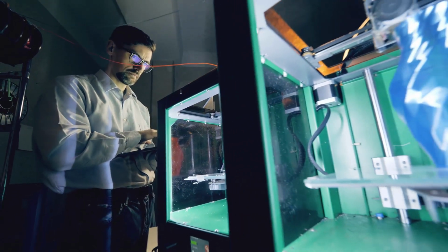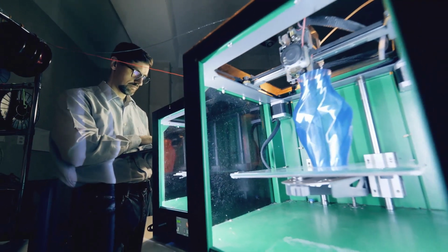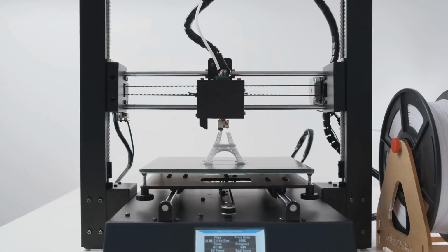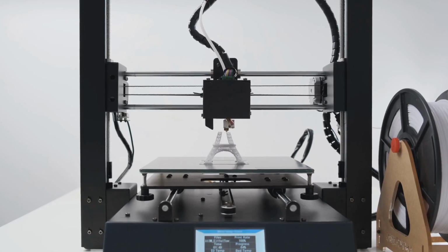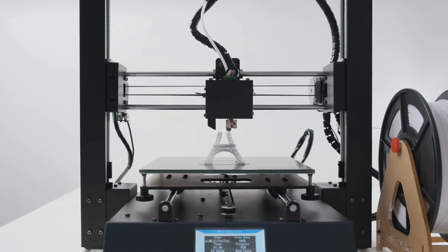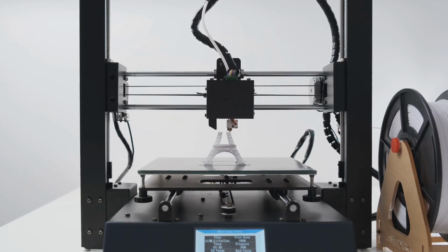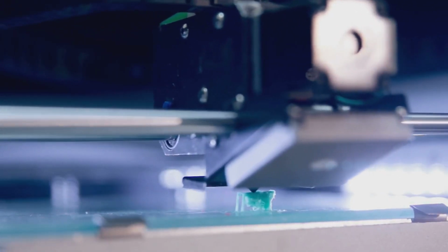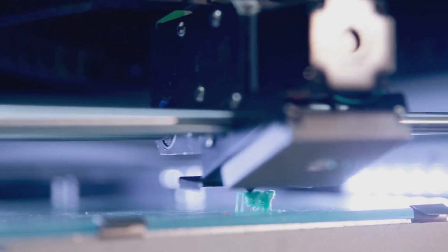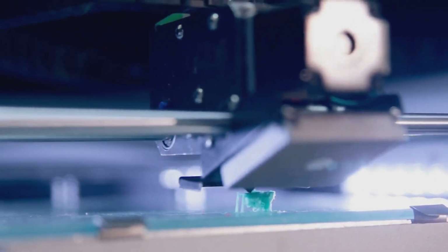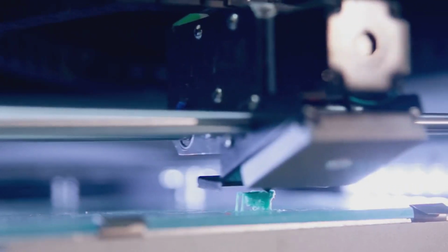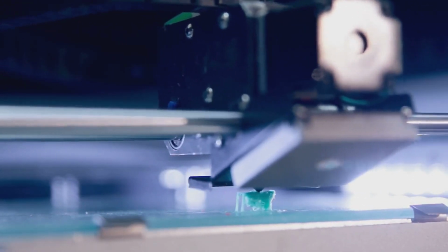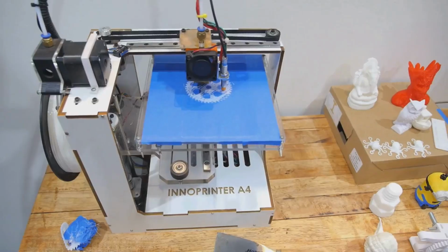Let's dive into some common G-code commands that you'll encounter in the world of 3D printing. G0, Rapid Move. This command tells the printer to move as quickly as possible to a specified coordinate without extruding any filament. It's typically used for non-printing movements like moving between different parts of the print bed. G1, Linear Interpolation. This is the workhorse of G-code, instructing the printer to move in a straight line from its current position to a new coordinate while extruding plastic at a defined rate.